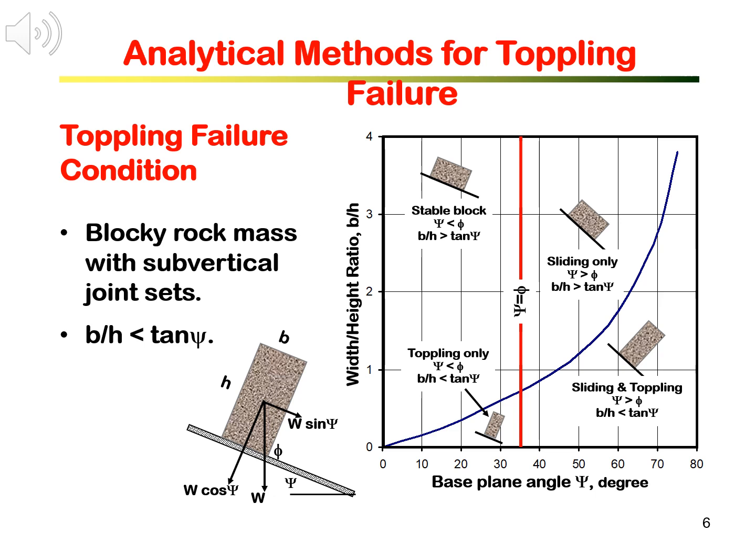Tipping over can be easily analyzed geometrically, as shown by the illustration below. When the force W is inside the width B, the block will not tip over. Only when the W line is outside the width B, the block will tip over around the base corner. The critical condition of tipping is expressed mathematically by the equation here: B over H equals the tangent of the tilting angle of the block.